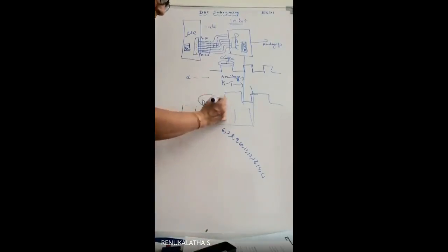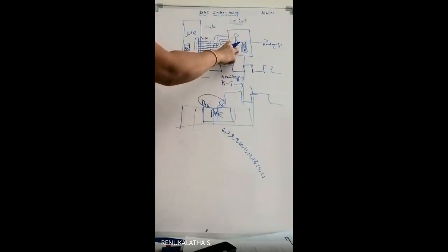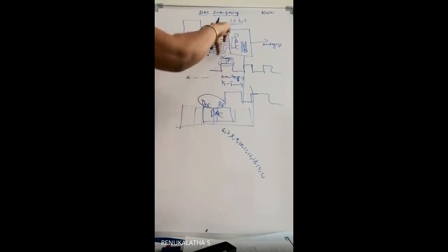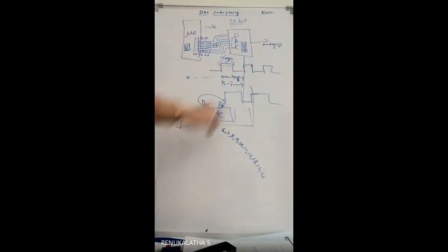These bits in the DAC register are meant for receiving the data, because it is a 10-bit data converter. It converts the 10 inputs received from the microcontroller into valid analog information. All other bits are not going to be used here. Follow this?